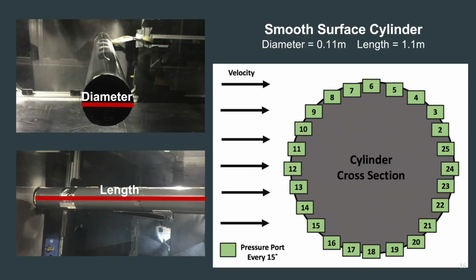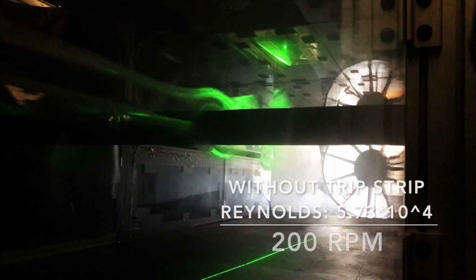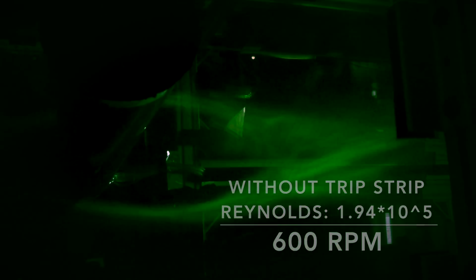During the experiment, the team ran the tunnel at 200 and 600 RPMs with and without a trip strip on the cylinder. When the team ran the wind tunnel at 200 RPMs with the smooth surface cylinder, they recorded 100 data points at each of the 24 ports. The team did this data recording method 3 times. Then they turned the tunnel up to 600 RPMs and repeated data collection.